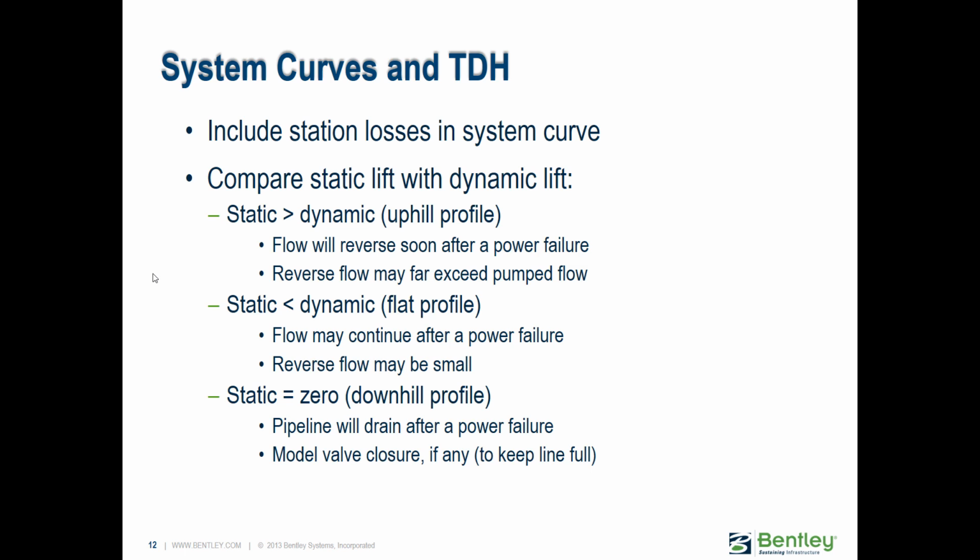So some points to make here is that you definitely will want to include any minor losses that you may have in the pump station to make sure that you're getting an accurate system head curve, and therefore your initial operating point of your pump is correct. And the rest of the slide just goes into the different types of profiles that you may have and the different components.